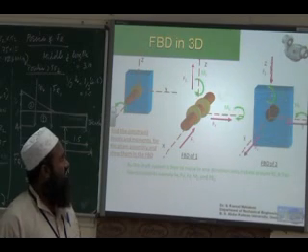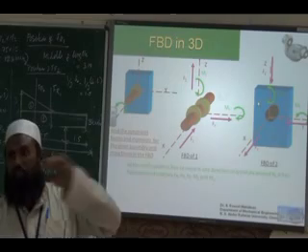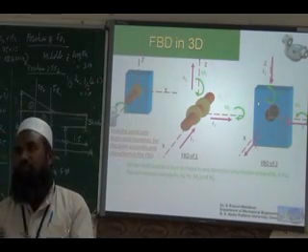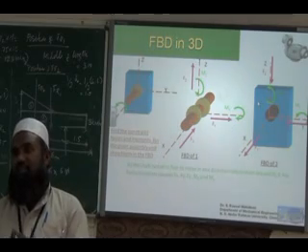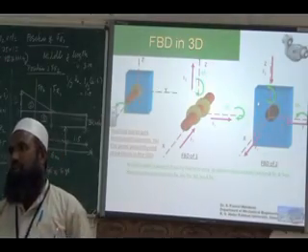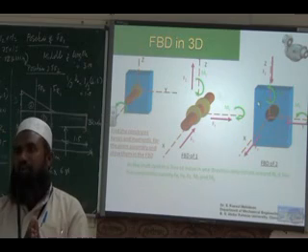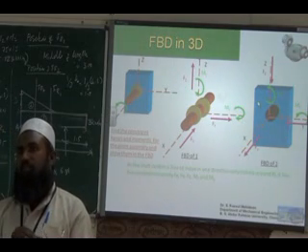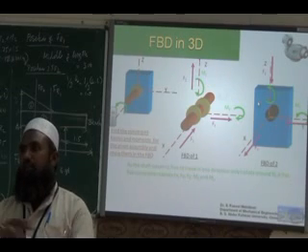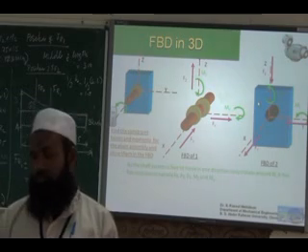Similarly, if you consider the free body diagram of the bearing, you will have the same moments and forces in the opposite direction. If you assemble them, the two reactive forces will cancel each other and it will be in equilibrium, so they are not moving. If you consider the free body diagram separately, we will show the reactive forces. If you assemble them to the actual support, the cancellation of forces will happen and it will bring the system to equilibrium.